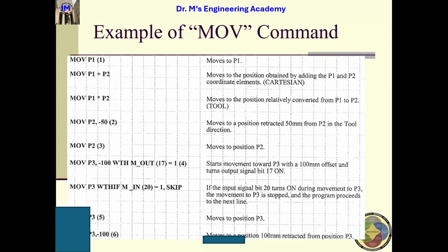That's the reason for MELFA BASIC 5, and we use the positive. You understand, guys? You need to be very, very careful. If I were you, I would write down: in BASIC 4 I use minus 50, and in BASIC 5 I use positive 50, to denote that I want to move to a location that is vertically above the desired location. So this is a subtle difference.